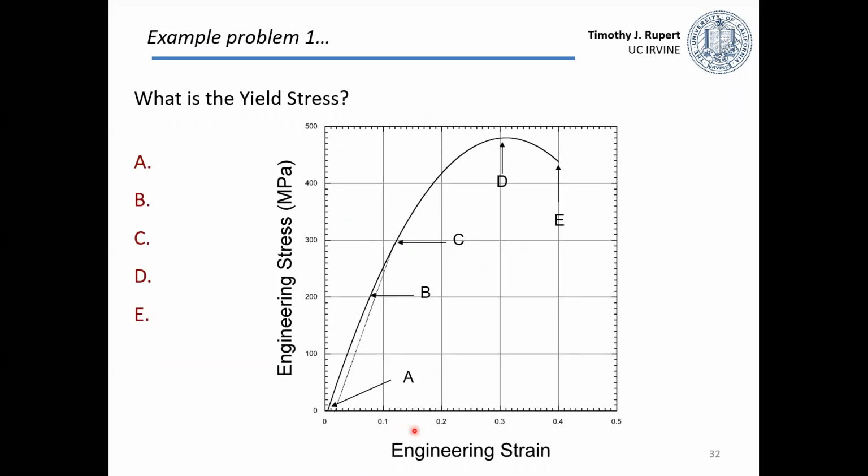All right, so let's test our understanding real quickly and ask ourselves which one of these points would be the yield strength of our material. All right, let's go through the ones it isn't. We just mentioned that the highest stress that our sample can hold is the ultimate tensile stress. Okay, so that's not it. This final point is where the sample breaks. That's not it. We're talking yield stress is the original place that we have plastic deformation. A is pointing to when there's 0 stress and 0 strain on the sample.